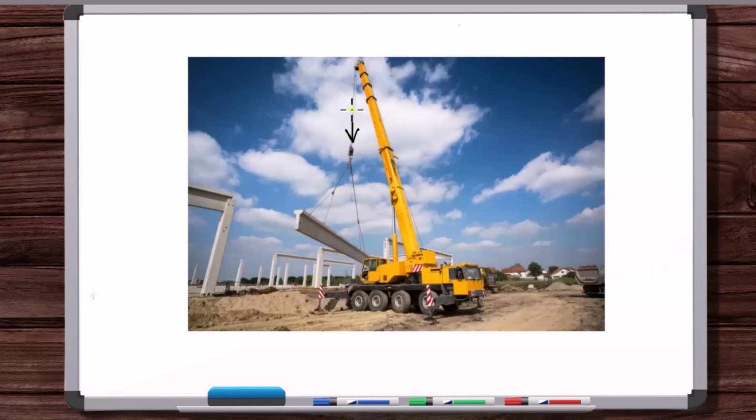Think about the skeleton. If you make this slack and then apply the load, the geometry doesn't change. All of that load going through the skeleton doesn't matter. It's all internal forces, so all you have to look at is the loads in the wheels going to the ground. That's the only contact points, unless there's wind.